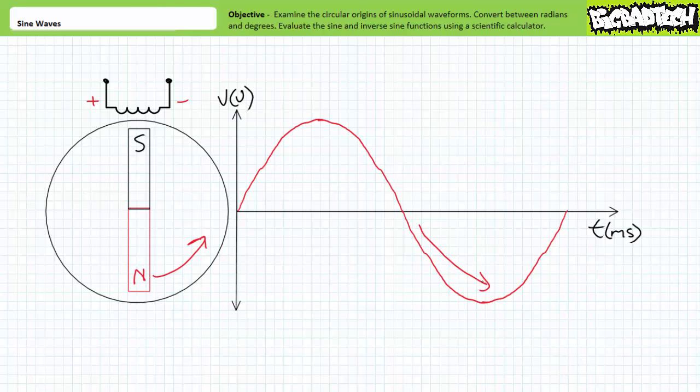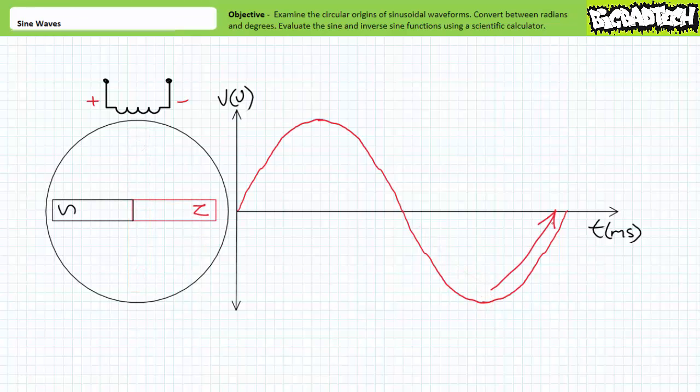The other half is essentially a repeat of the first, only a negative voltage will be generated since the south pole is on the business end. As the rotor continues to drive counterclockwise, the south pole gets closer and closer to the stator, and induced voltage bottoms out at 270 degrees. As the rotor continues to drive counterclockwise, the south pole gets further away. The induced voltage during this quarter is still negative, but decreasing in magnitude. At 360 degrees, or 0 degrees, we've done a full circle, and the north and south poles are again equidistant, and the induced voltage is 0 volts. The process then repeats itself.